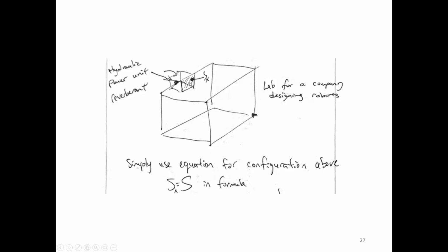If you're right up here, the distance isn't going to matter, right? If you're within 75% of this dimension, the distance isn't going to matter. But if you are out here, it is going to matter. Whatever the ratio of this distance to 75% of this is, then you use that relative SPL to make a further reduction for what you get from your noise reduction for this point out here.